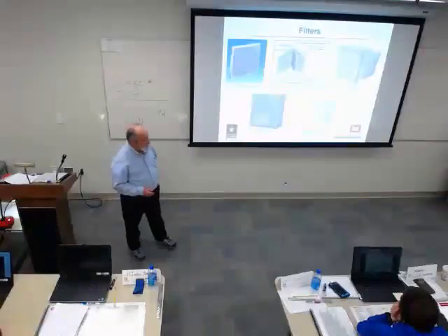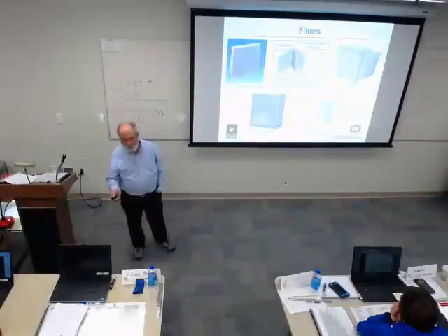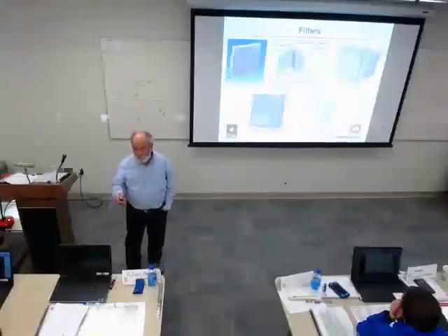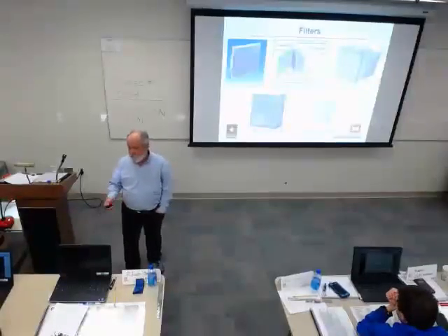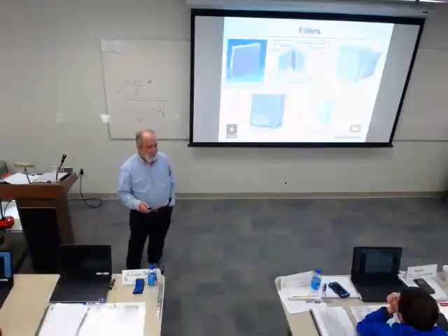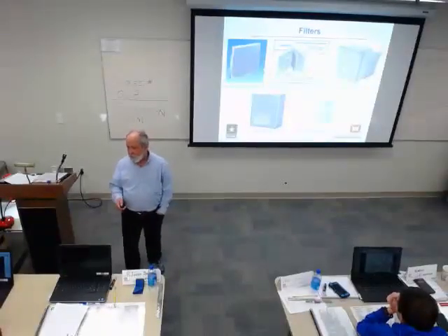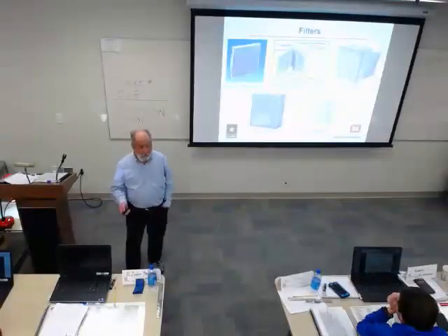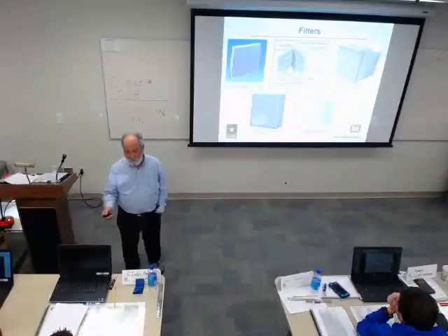Most of our filters are pleated media, and just so you know, you really increase the life of a filter when you go to a deeper one. A 4-inch pleated filter has much more life than a 2-inch pleated filter. The reason is the pressure drop through a filter is a function of the resistance of the filter and the velocity squared of the air going through.